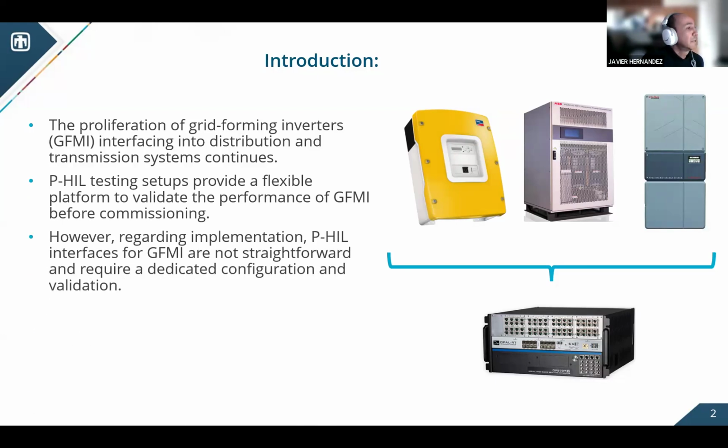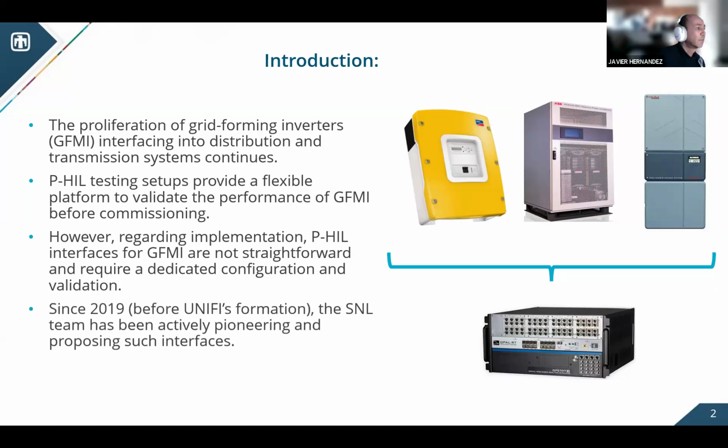However, the implementation of these power hardware in the loop interfaces is not as straightforward for grid-forming inverters as it is for their grid-following counterpart. For this reason, we have to have a dedicated configuration and validation for these grid-forming devices. It is important to mention that even prior to UNIFI's inception, the Sandia team has worked very actively in pioneering and proposing this type of P-HIL interfaces for grid-forming devices.